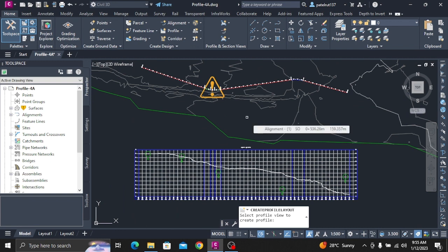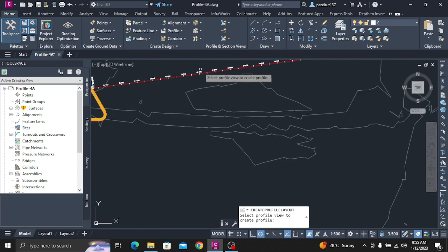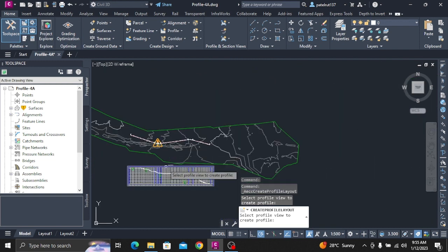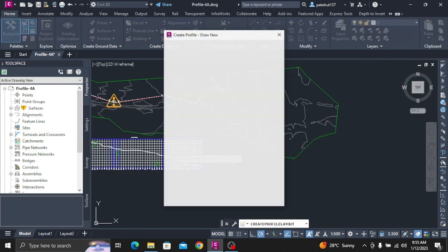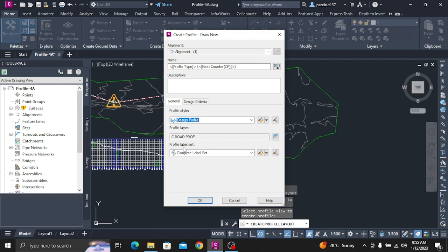When you grip edit a projected feature line or 3D polyline, the corresponding elevation of the source object is adjusted. Press enter. Close the AutoCAD text window. Modify the display of projected objects in profile view. In the right viewport, select the profile view grid.